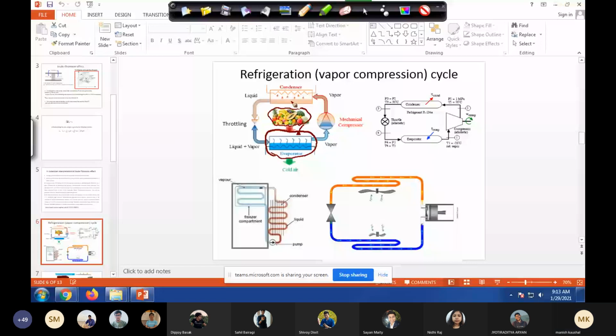So this is an evaporator. From this evaporator, since heat is coming in from the food item, this is actually a liquid vapor mixture in the evaporator. Then this vapor enters a mechanical compressor. What is meant by a compressor? We do extra work, shaft work. And due to this work, we can compress the gas.